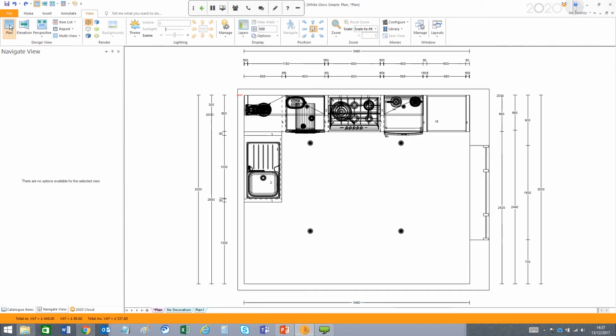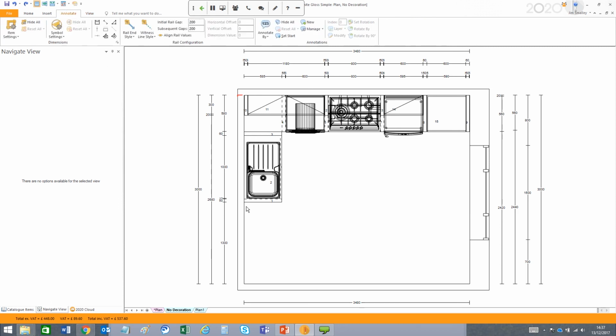Okay. We'll go back to our plan view. Let's have a look at our plan view here, and other elements that we've added. Fusion has a variety of functions, such as the ability to add products using the single or multi fixture tool or the measurement tool, but also things like our manual dimensioning tool, which rely on what we call snapping points or hotspots. In version 5 and earlier, it was sometimes difficult to visualize where you were actually snapping to, because sometimes there would be many areas where it was picking up.